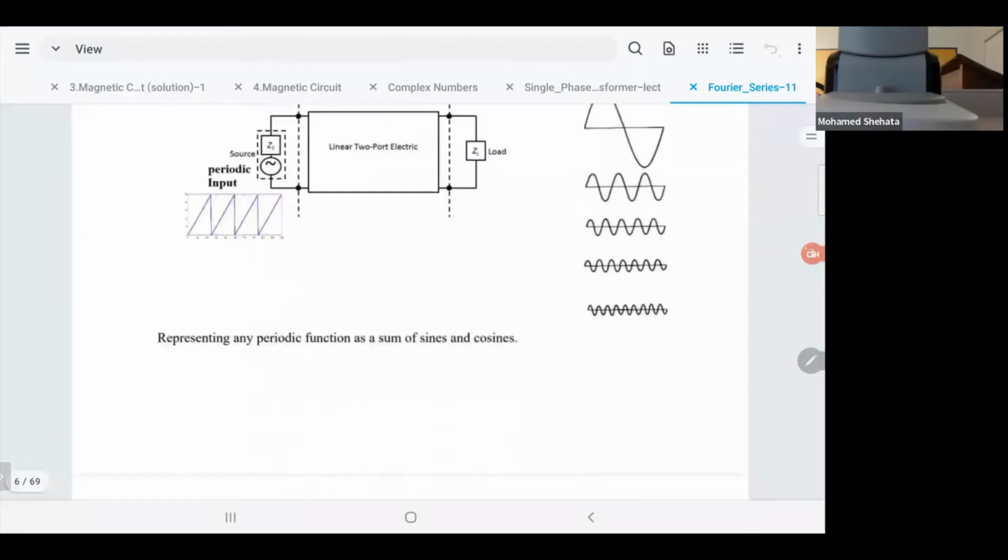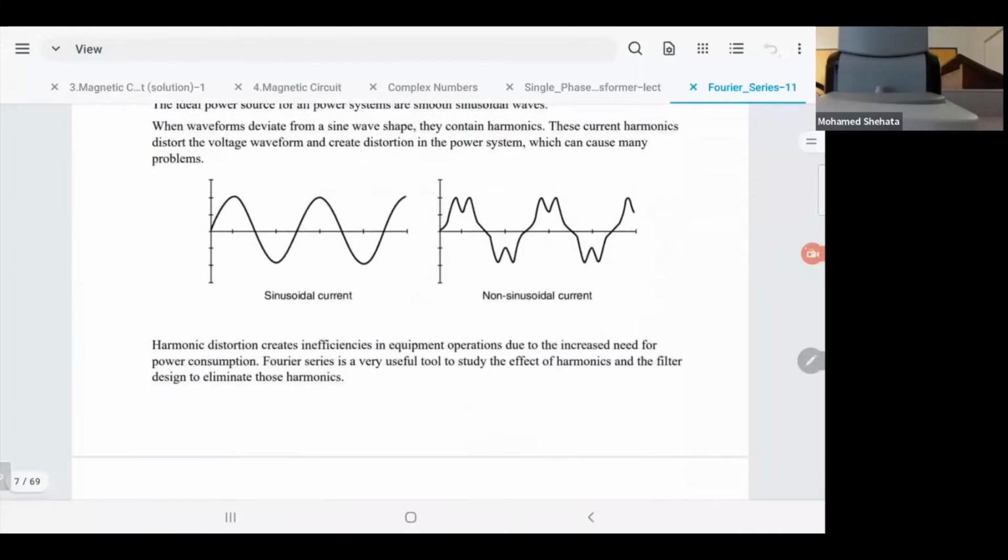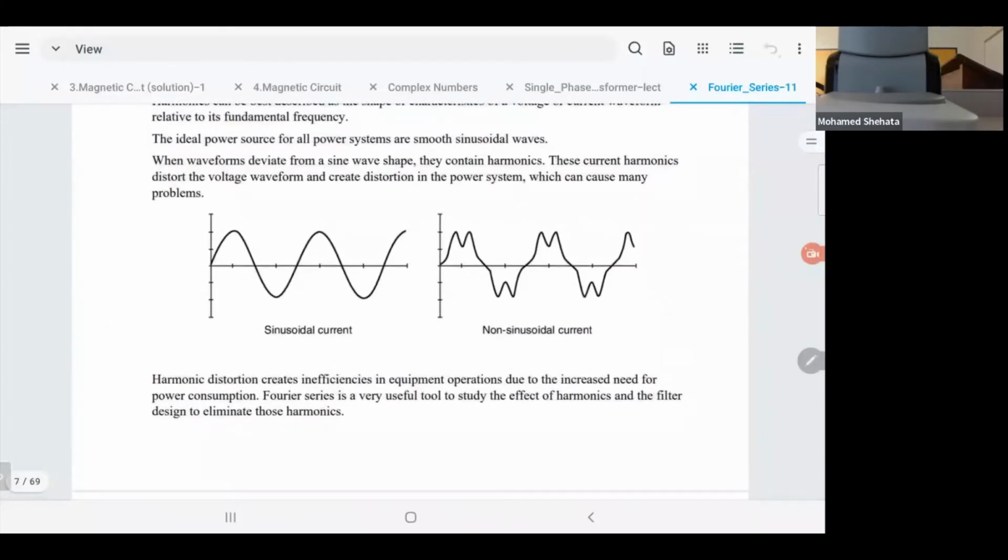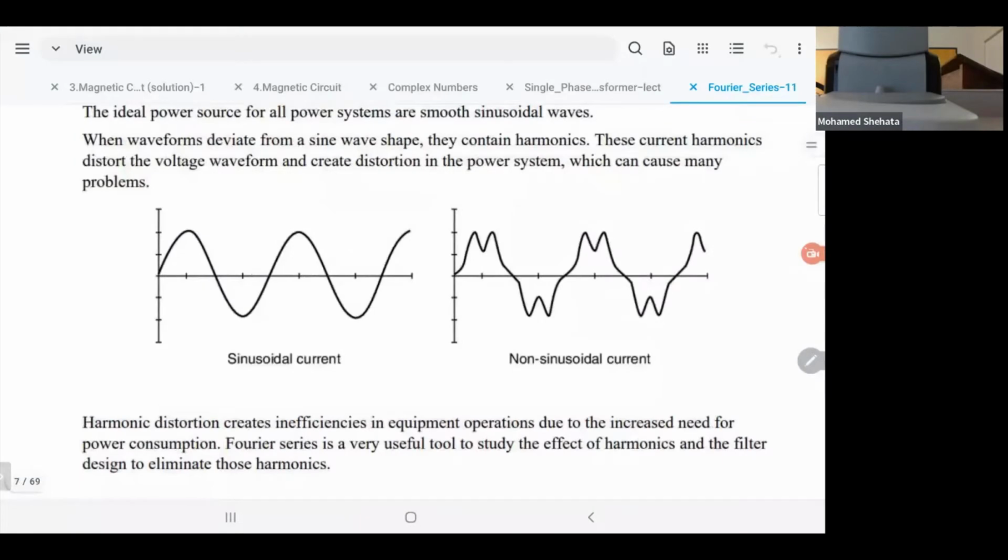This is one that I dealt with. I'm working with something like that. But there are other things. In electricity, power supply. The power supply provided by the utility company is a pure sine wave, like this one on the left. That's a pure sine wave, because the generator is rotating and all the conductors are distributed over the generator in a sinusoidal way, and the output is 3-phase, of course.